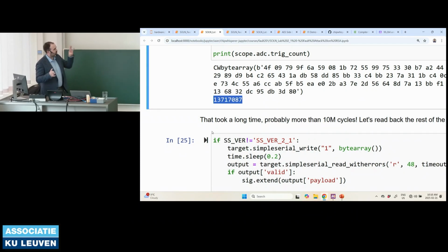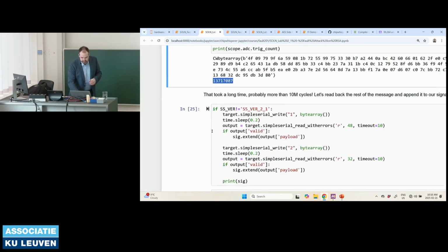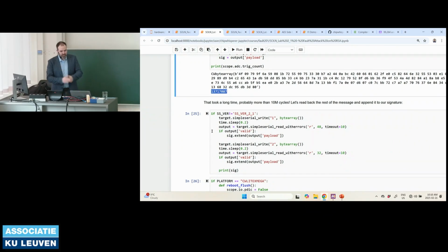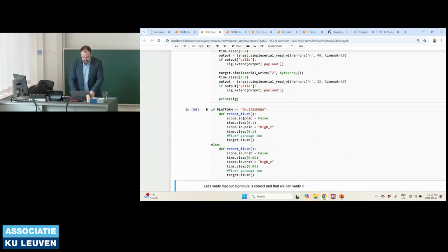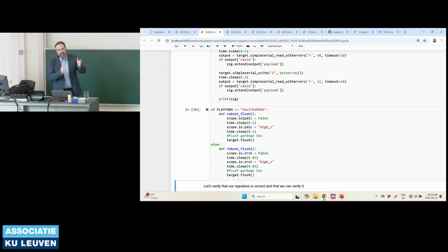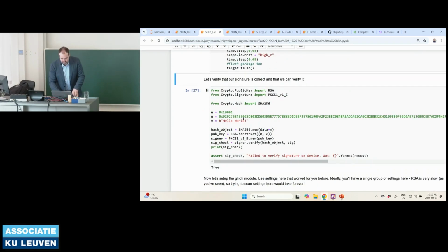I just have to hit roughly one half or the other half, which is what it's doing almost all of the time. So I can just kind of guess with my fault injection attack, okay, let's just set it to half and a little before half. So that's exactly what I do.